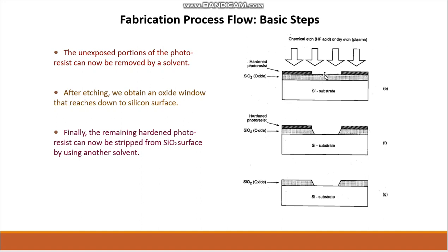So we need to begin with simple transistors, and when we talk about simple transistors, we are generally talking about digital transistors like field effect transistors. In a field effect transistor, we know the basic three electrodes are there: source, drain, and in between these two electrodes there has to be a channel. Through the channel we need to connect the gate electrode. That is why, to have a bare oxide window, we need to follow these processes, after which we need to access that particular channel, that particular substrate, that is the body.